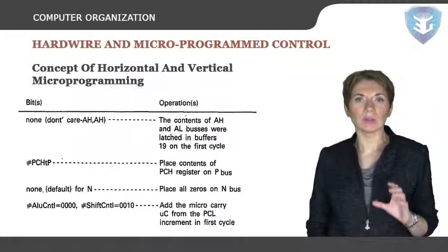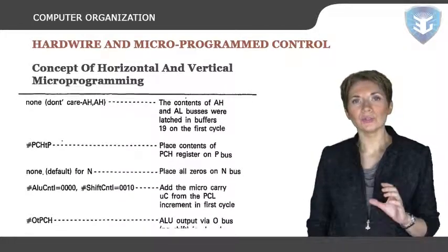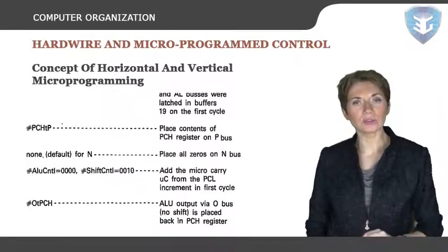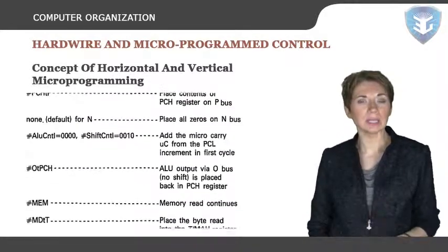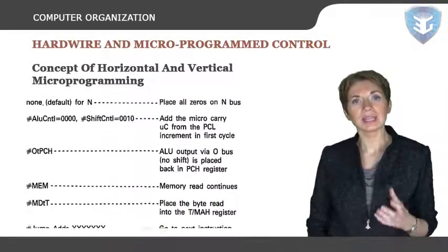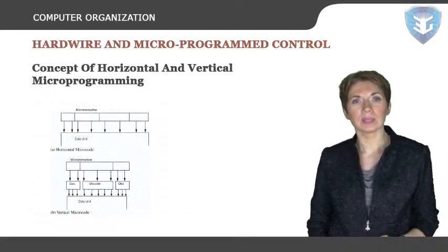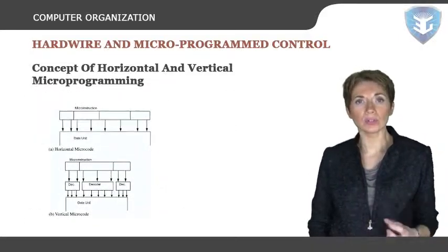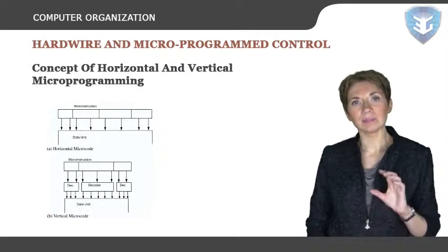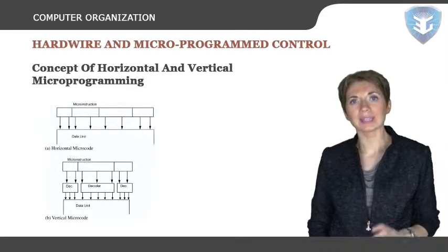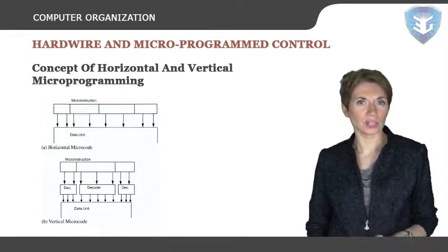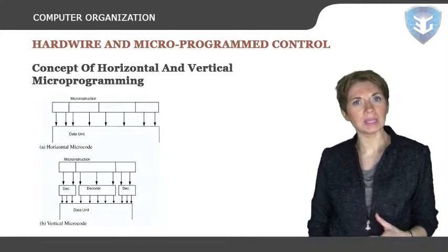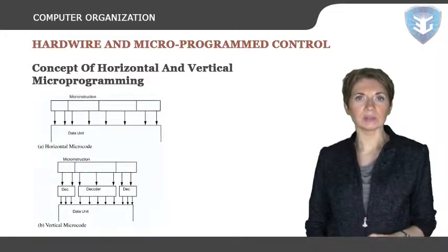The meanings of the microinstruction fields do not depend on the meanings of other fields. None of the fields can have two or more different meanings for identical values contained by that field. The disadvantage of horizontal microprogramming is that the bits of the microprogram word cannot be used efficiently. Not all microinstructions allocate useful meanings to all the available fields.